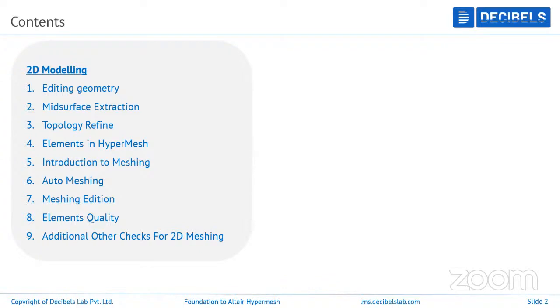I'm not going to alter the CAD. I'm just creating or deleting surfaces within the boundary of the geometry to create the elements. Being a CAE engineer, we are not supposed to change any dimension or any features in the geometry. We can only play with the unit size: if the design engineer has done it in millimeters, we can do it in meters also. In a very simple manner, the CAE engineers work.